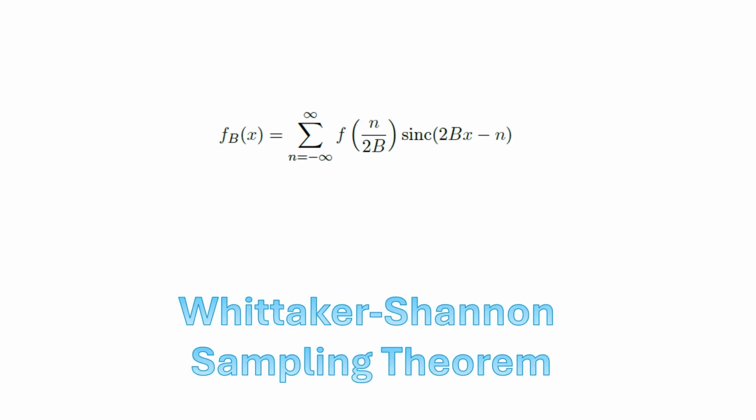To understand what it would mean to sample the mutual intensity, we step back to this slide from episode 4 of our series introducing the Whittaker-Shannon sampling theorem. And of course, you'll recall that the sampling theorem says that if we sample the signal with a period equal to or smaller than the Nyquist period, which would be 1 over twice the bandwidth, then we can exactly represent a band-limited function.